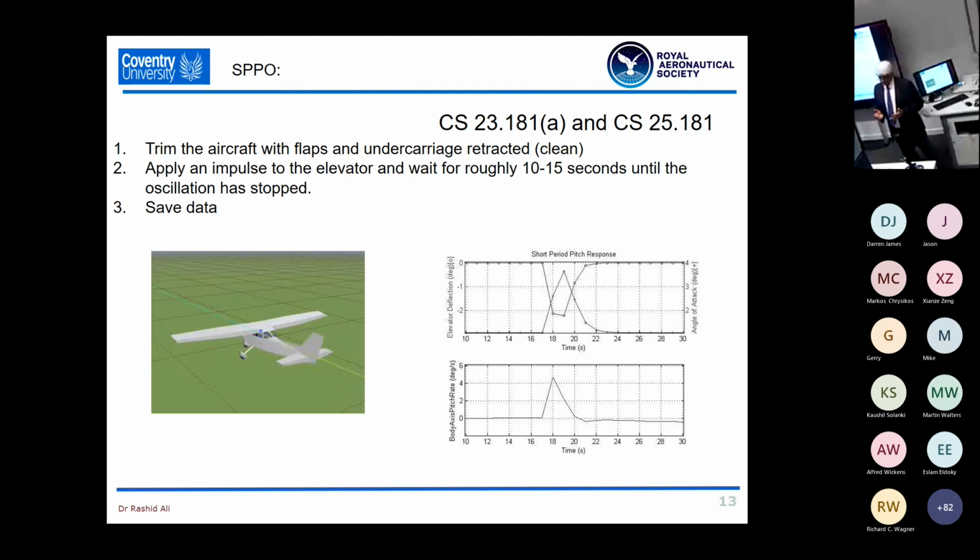In the real aircraft, the control column, especially in light aircraft, is connected directly to the control surface. So when I move the control column or the stick or the joystick, I can not only feel the dynamic pressure relayed through the control runs, wires, etc., but the aircraft responds pretty much instantaneously. Whereas in a flight simulation environment, you have the input of the joystick, which is being read by the computer. It then processes that input, then evaluates the effect of flight dynamics, and then displays it.